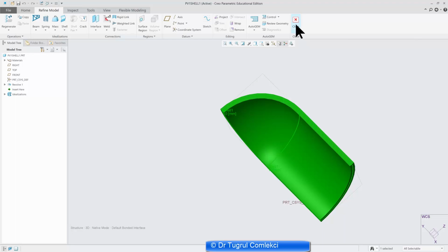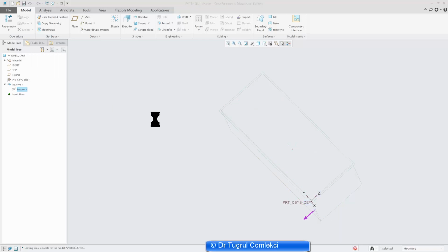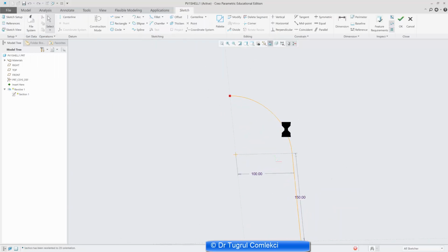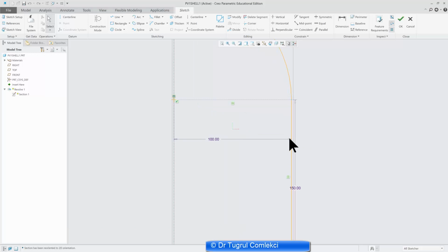And we can also now ensure our sketch was done accurately. So if we go back to our sketch, that sketch was done at an internal radius of 100 millimeters for the cylindrical portion and also for the start of the spherical portion. Now if we added 10 millimeters of thickness on either side of this line, which is representing the mid-plane, the actual inside radius of this vessel would be 95 millimeters.